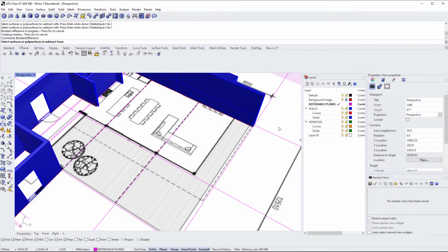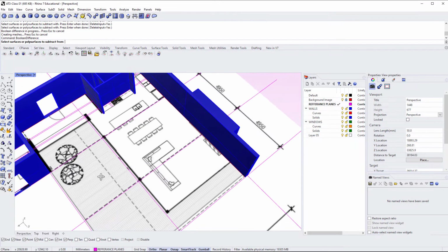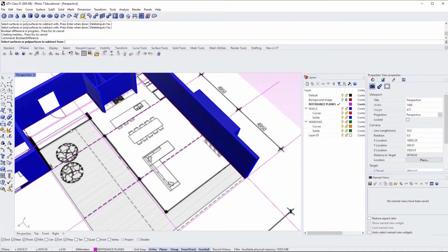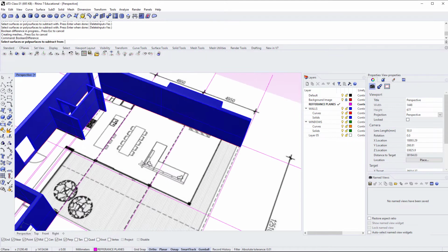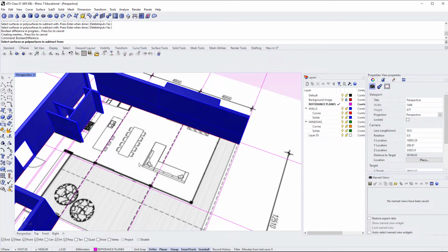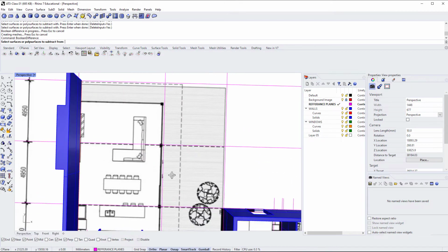We want to now rationalize our glazing walls, particularly when we first walk in, we have this glazing wall over here. We then have the two glazing walls that enclose our living space. So again, we want to construct blocks, and we want to try to construct as few blocks as possible to cater for as many solutions as possible. This is no different to real-world principles, where you won't want to be manufacturing an individual window size for every single glazing panel. You'd like to rationalize them into maybe 2 or 3 different types, and then have those manufactured at scale. So let's take a quick look at how we could break this up.